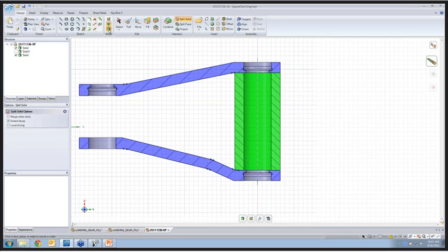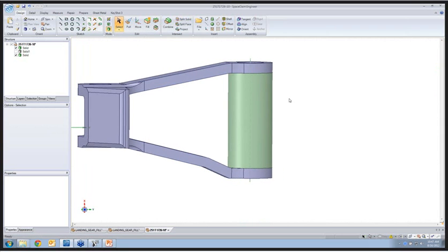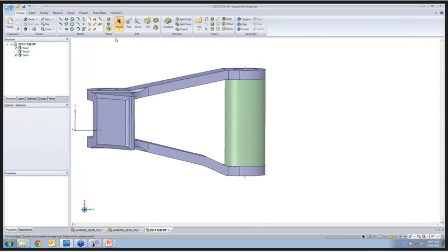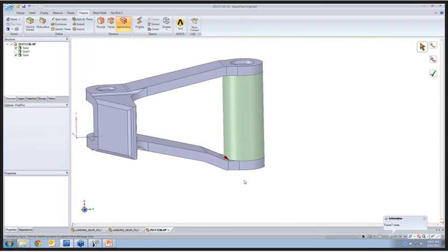But to play it safe, you don't know if your model is perfect. That is, if the fit between your fixture and the model is exactly the way you want it, just right. So we give you a tool called interference detection. With interference detection, you can find out exactly where you have problems. That's something I couldn't really predict. It shows up in bright red where the two bodies interfere. And so now I know to go take care of something over there.